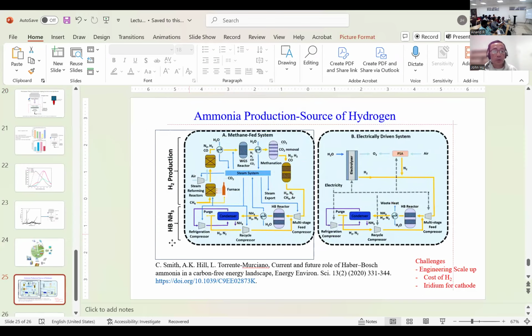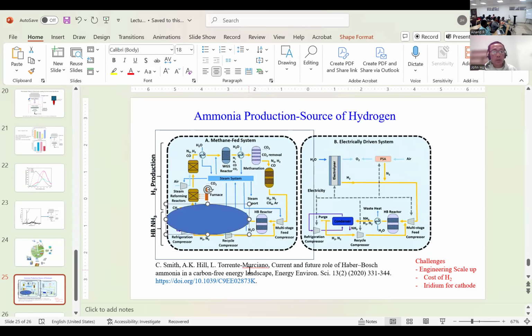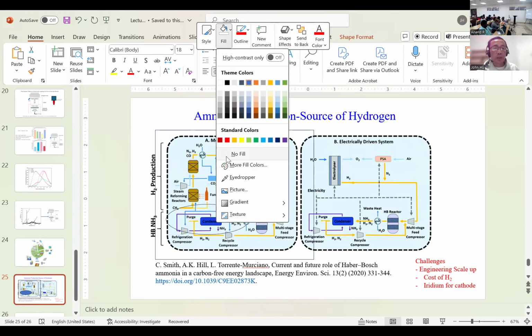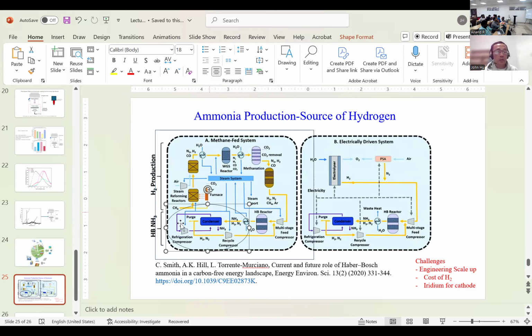So basically, if you look at my cursor, and this section, look at my 6th section. It costs you a lot of money. If anything fails in this section, which I covered, you have to shut down the plant. But if any other location fails, they have redundancy. They can afford the A and B. Remember I said you have pump A running, you have pump B on standby. Whatever is in this circle, you don't have that option because they are so expensive. If any of these three equipment goes down, you have to shut down the whole plant.